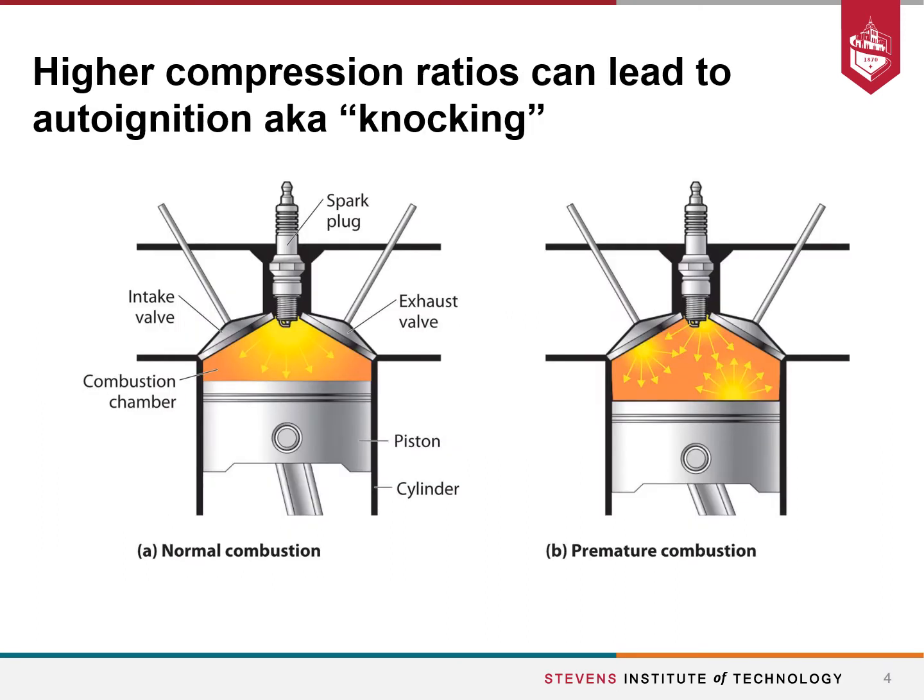What do we mean by knocking or auto-ignition? On the left here is what might be termed a normal combustion process. We compress the fuel and the air and then burn it using a spark to ignite the mixture. And so we have a spherically expanding flame that's fairly predictable. It starts off near the spark and then expands through the chamber.